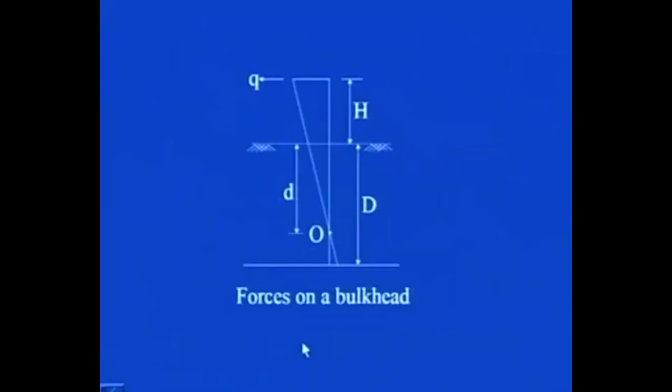So, here I am assuming that the lateral stability is only due to the soil present in the neighborhood. Under the application of the horizontal load Q, it has a tendency to rotate about a point O above the base of the well, under the action of this horizontal force Q.